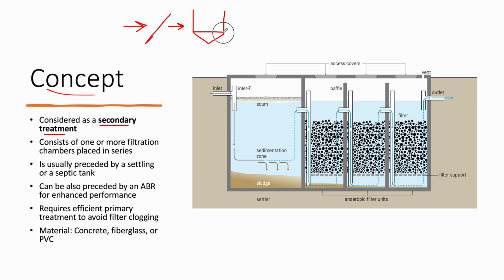So we will have the formation of a sludge. And also we will remove the floating materials, so the scum, anything that will float. So this is the primary treatment, or the first stage of treatment. Then we have the secondary treatment. Usually in this secondary treatment, we remove organic matter. When we say organic matter, we mean the main pollutants like the BOD, the COD, nitrogen and phosphorus. So this is the bulk of the treatment.